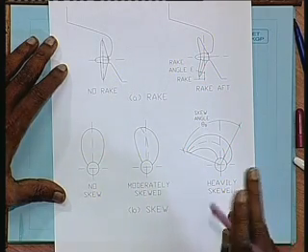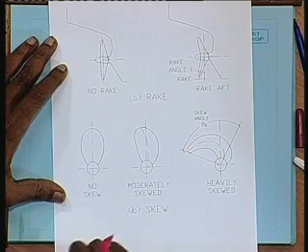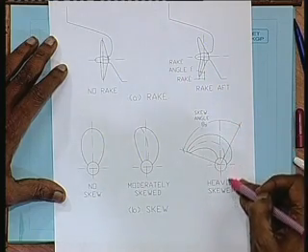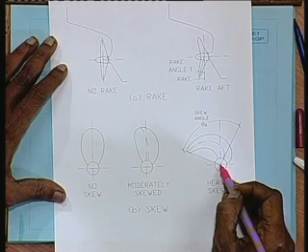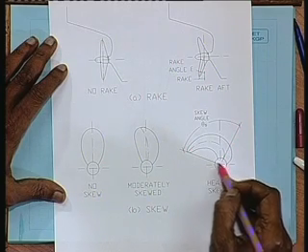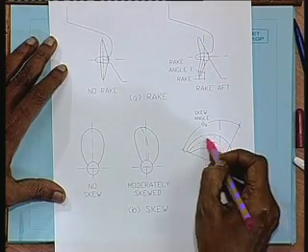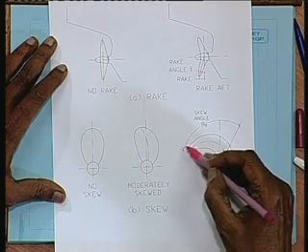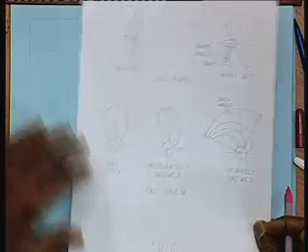And you can see the center line of each blade plotted here, and the measure of the skew is generally the angle between the propeller non-skewed axis to the line joining the propeller center with the tip, that line. This is the skew line, and the measure is the skew at the tip, that angle. Is that clear? So, this is normally how propeller rake and skew are designed.